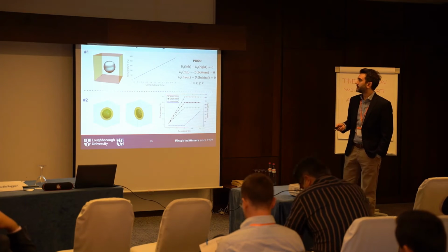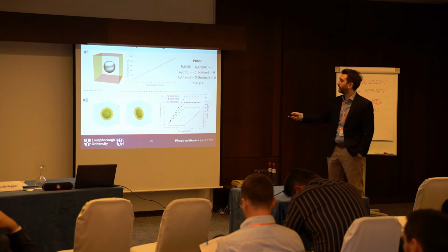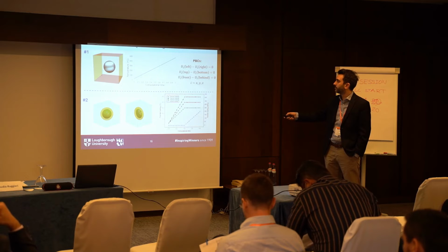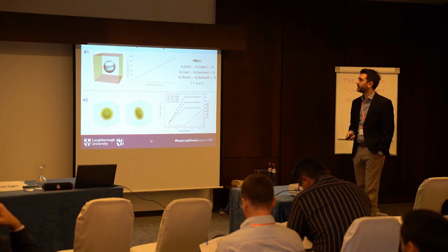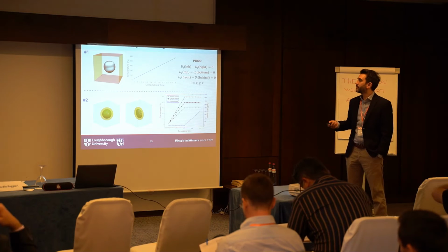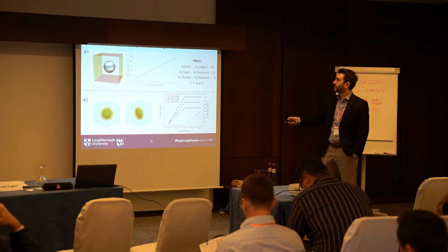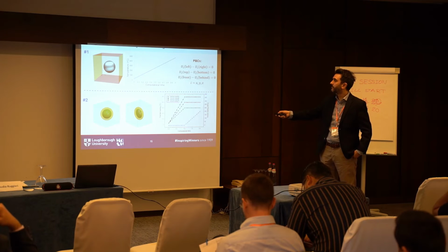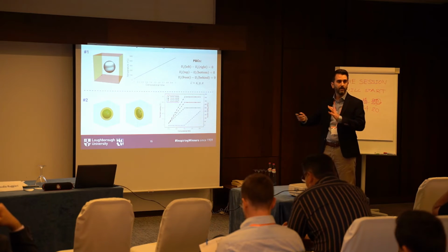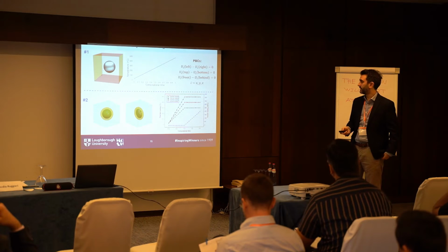These are now the boundary conditions and the loading conditions. So the two models I showed earlier, the top one, I will not apply any mechanical load, the temperature will only be increased from 0 to 500 degrees, as we have done earlier. And because we talk about homogenization here, periodic boundary conditions, meaning the top and bottom have the same displacement, left and right same thing, front, back, they deform. So essentially you have a unit block representing uniform material.